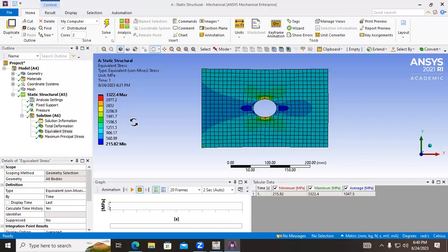All right, one last thing before you guys go today, which is saving these files. Saving an Ansys project is actually not as straightforward as you think. Because there are multiple different programs that Ansys uses, there are also a lot of different files that need to be saved, because you need files for the CAD file, files for the mesh, and files for the boundary condition information. They're actually all stored in separate files.